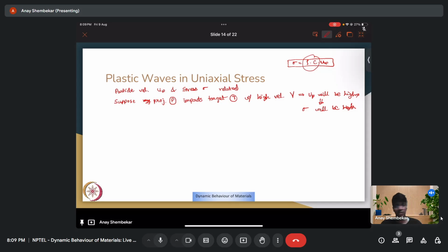This is important because if we look at the stress strain curves, materials will have a yield point, especially the materials which exhibit ductility. So if I plot the stress strain curve, it would have a straight line with Young's modulus E, then a small slope, and then this could be your yield point sigma y.